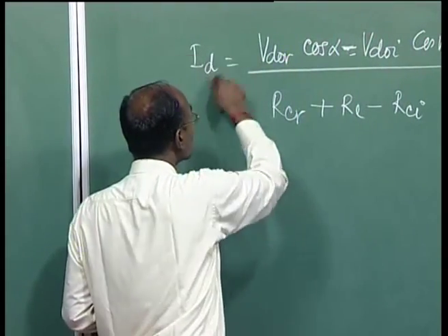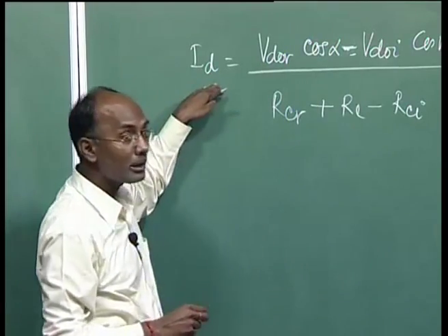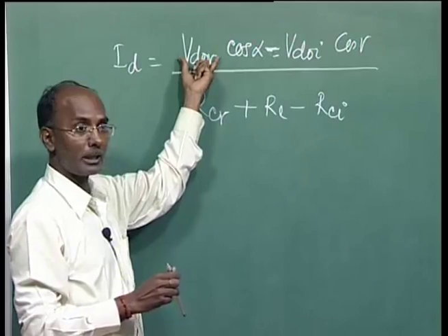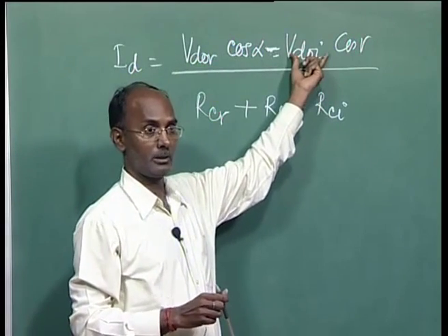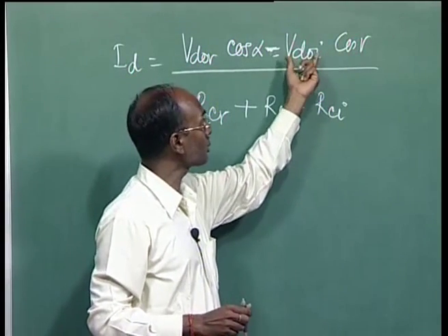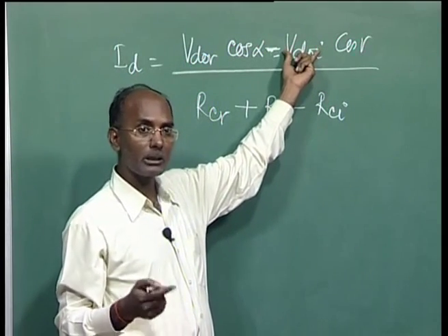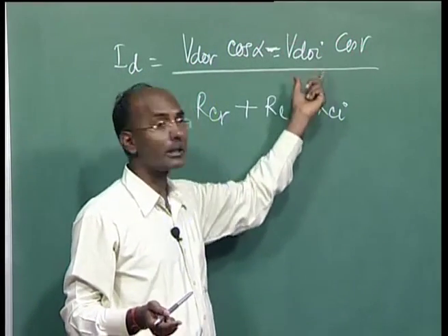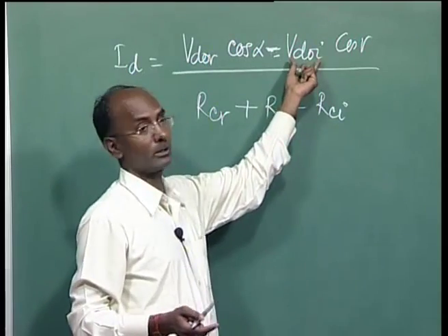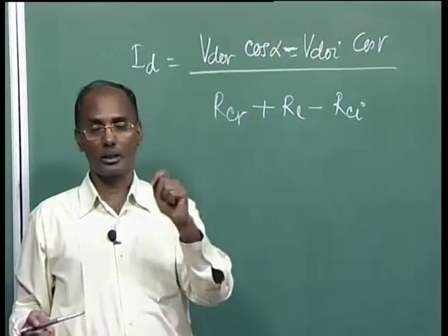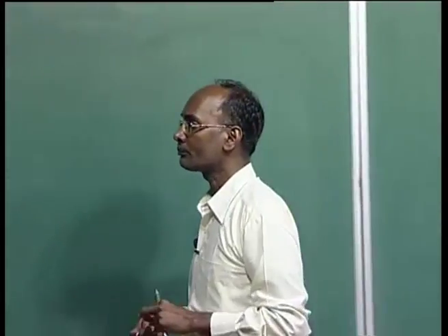Even though this controller's current is not maintained to its rated value, then we have to exercise either this end tap changer or this end tap changer. So it is preferred to control the tap changer at this side because the voltage has increased on that side. So it will wait, there is some time delay, and it will try to decrease the tapping so that we can maintain this. Even though it is not fulfilled, then we have to go here to maintain the current here in this link.